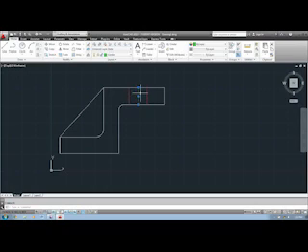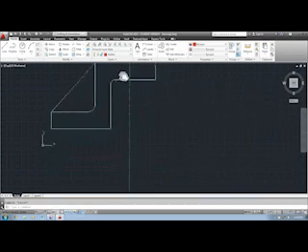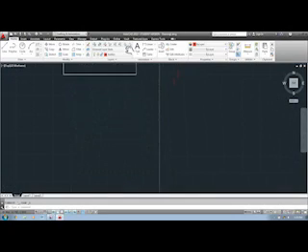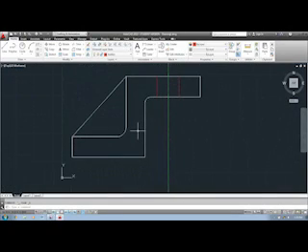Well, actually, this should probably use the X line command instead. Nice infinite line there. And that does need to be the center line type. The X line continues out indefinitely, so you can't actually zoom to it. So that's something of note.